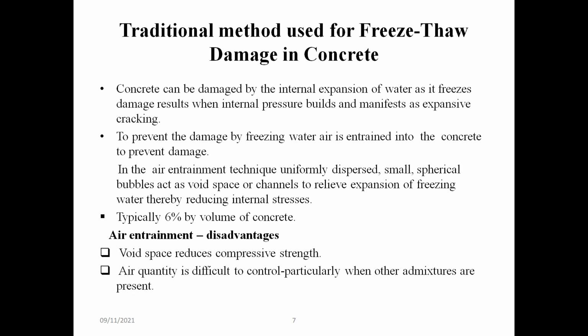Traditional method used for freeze-thaw damage or freeze resistance in concrete. Concrete can be damaged by the internal expansion of water as it freezes. Concrete contains voids. Now, these voids may also contain water. If they contain water and if the surrounding environment temperature goes below the freezing point of water, then the water inside may become frozen.